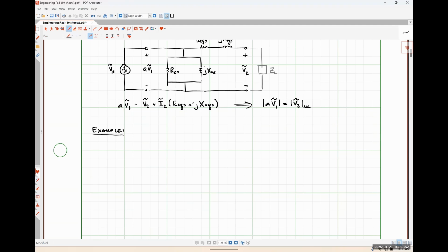Now, specifically, the service that's coming into our home is from the secondary side of what we consider to be a step down transformer, because when we transmit power over longer distances, we always want to do it at a high voltage because we have lower I squared R or ohmic losses.